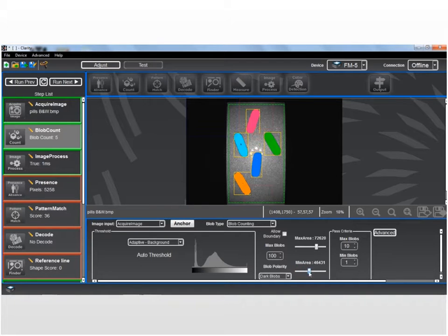I'm going to move this a little tighter. 46,000 I still recognize. Okay, 54,000, I start to lose them. So let's move this up to somewhere in between there. 54, 51. And then I can move this down as tight as I wanted it to be, for however discriminating I want to be for the size of those particular objects.